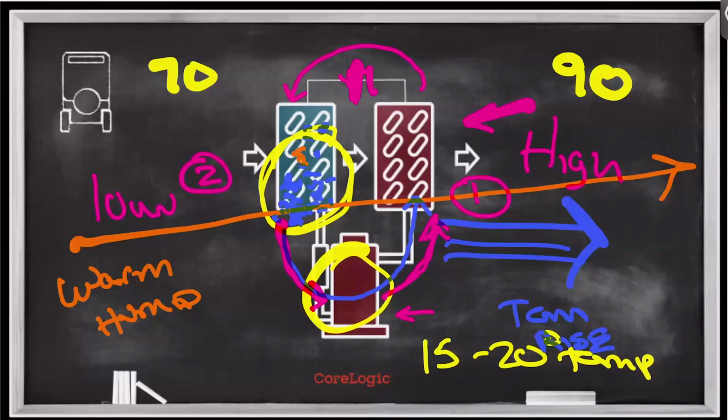But a far simpler way to understand performance is this temperature rise. If you're getting a 15 to 20 degree temperature rise, that indicates that you are condensing a significant amount of water onto that dehumidifier's coil system, and that dehumidifier is performing well. There isn't necessarily a fault with the dehumidifier. Now, did you install too few? We went through that analysis earlier on in the conversation. That's a potential. But the dehumidifier's performance overall, the way it's operating, the health of that system is good, right? So at least it gives us that information so that we can rule out whether or not that dehumidifier is operating properly.